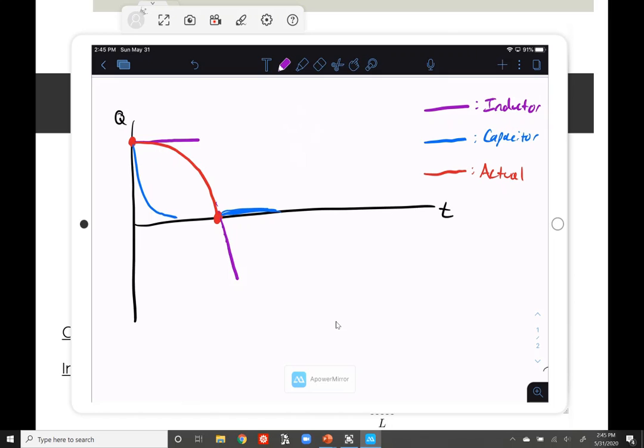The inductor wants us to overshoot because getting to this discharge state meant building up a lot of current, which you can't just take away instantly. So you wind up overshooting the fully discharged state. And we wind up here, where finally we got to this spot where the current got back down to 0.